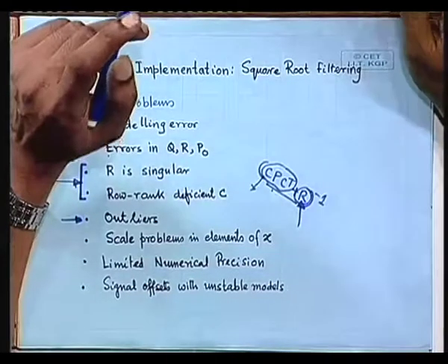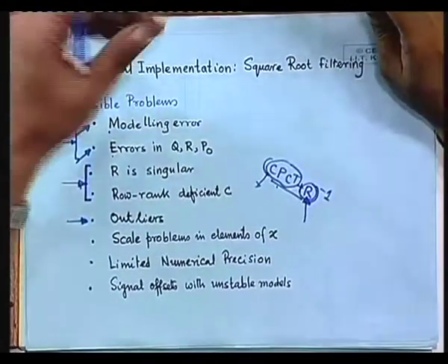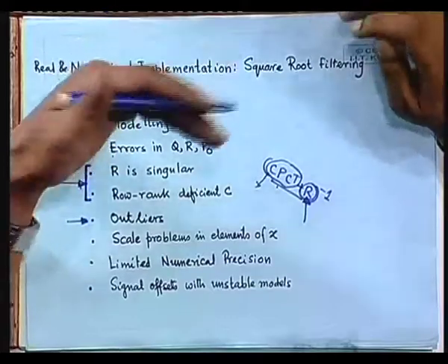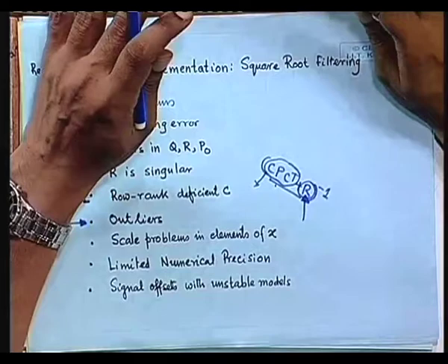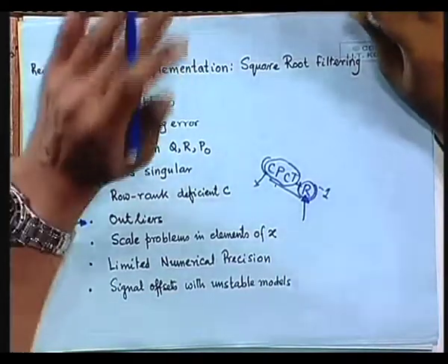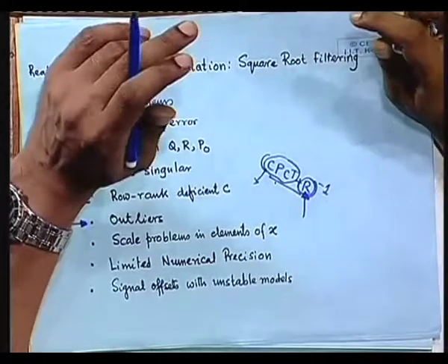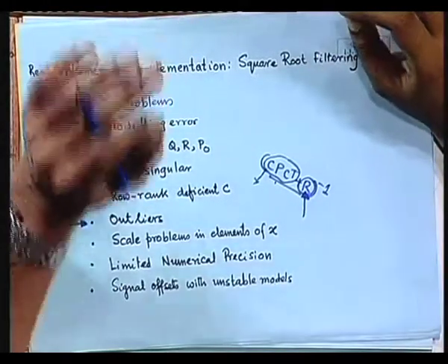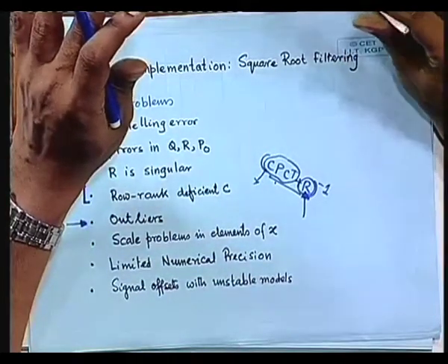If you are not aware of those, and if you don't tackle them, first of all see whether you are having such samples. If you have such samples, it is better not to update based on those samples, because they do not really belong to the probability distribution which you have assumed for the filter. They are very sporadic signals which actually belong to a totally different probability distribution.